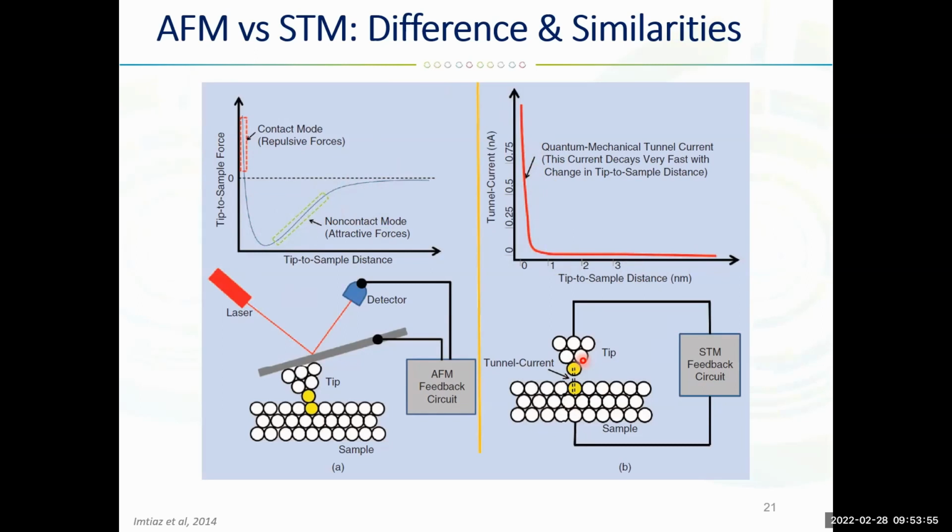If we compare AFM with traditional microscopes, let's say the optical microscope or scanning electron microscope, and what kind of dimensions we can measure: in practice, for areas greater than 100 micrometers, it is hard to measure with AFM and doesn't make much sense. But for higher resolution, going to atomic resolution, AFM is a very good example of an application of the microscopy.